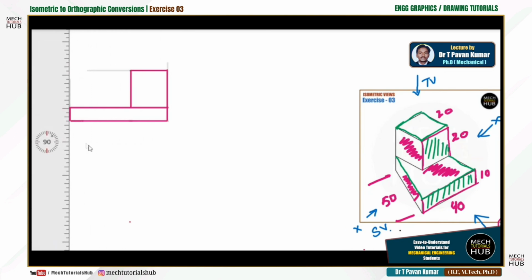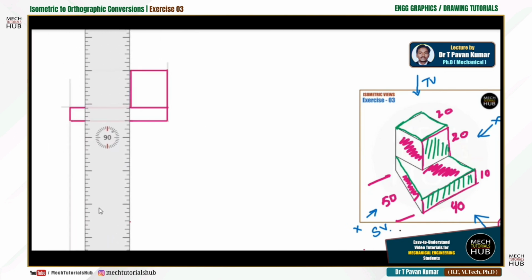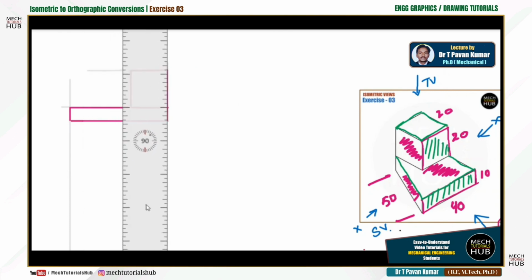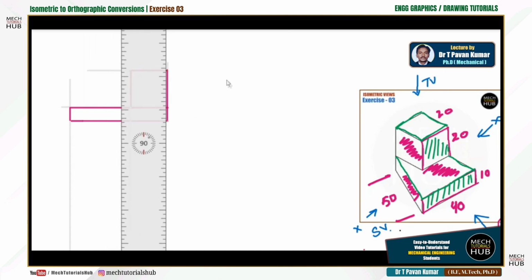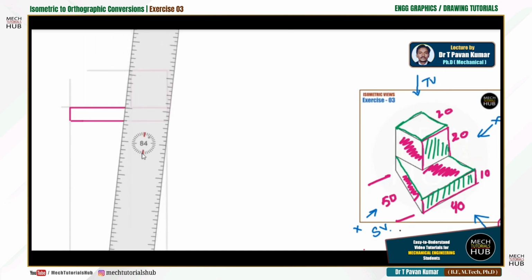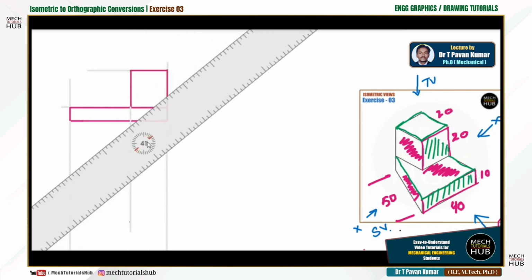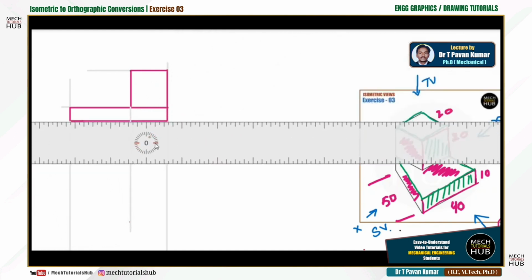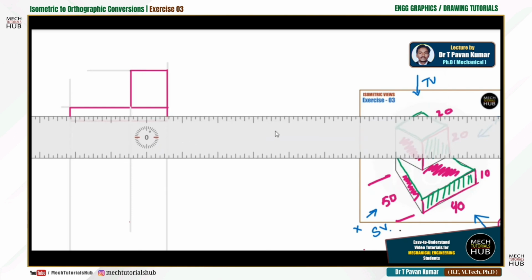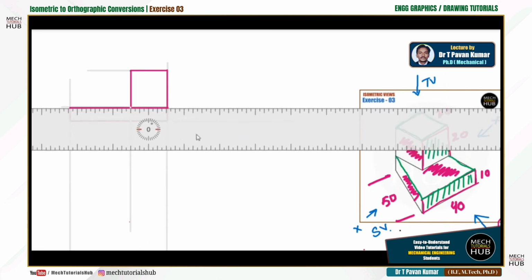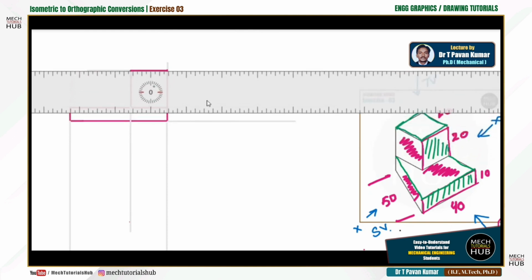Now again drop extensions up to infinite distance at every instant, at every intersection, vertex point, meeting point. That will help you draw the rest of your views. Similarly, rotate the scale and draw the extensions for the side view also. At this bottom or base, one line, move your scale or the drafter to the next height or intersection, next line, any infinite distance. Construction lines can be drawn something like this. All right, till here it is fine.